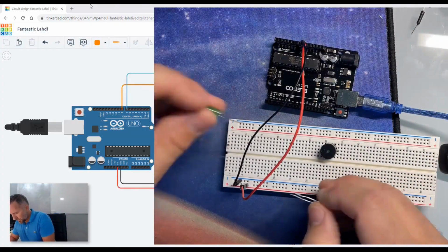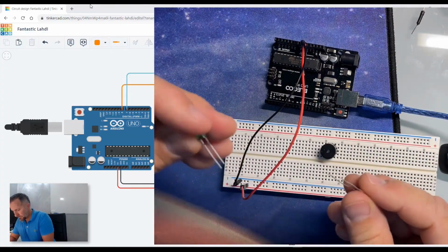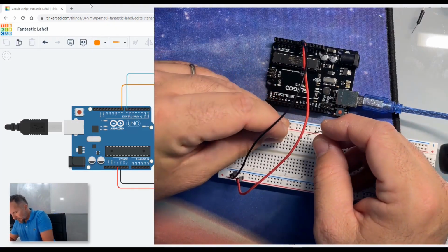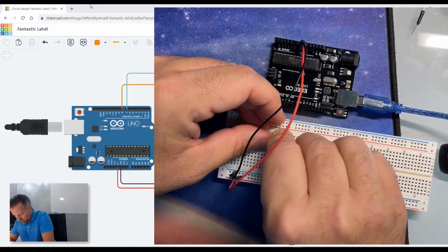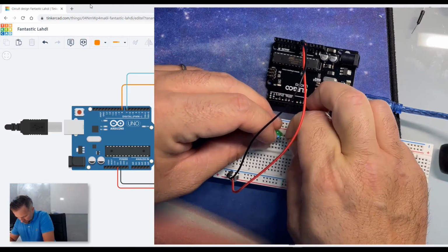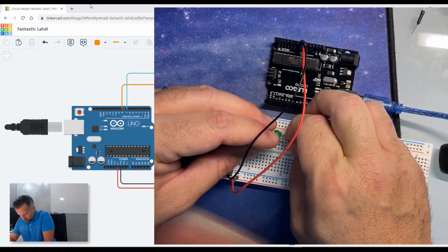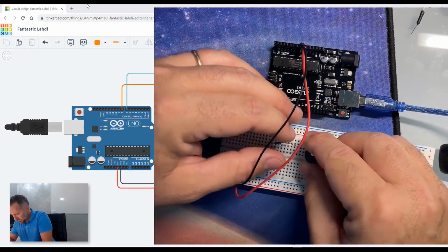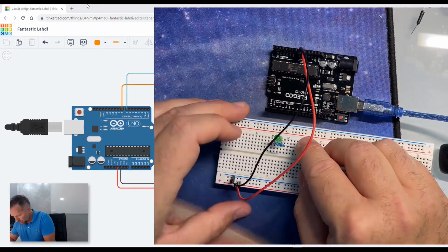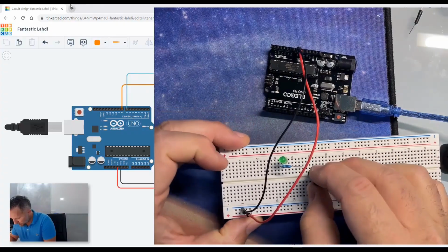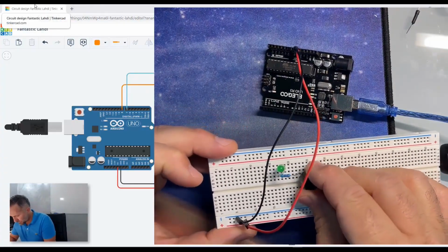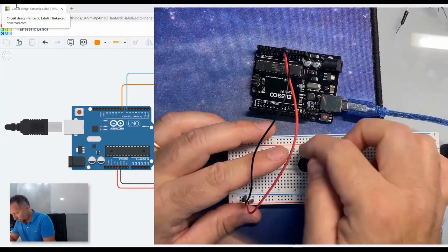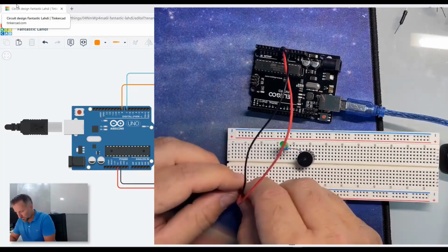We set up an LED that can light up together with the buzzer. So we place them on the same row. Then I connect the end of the resistor that powers the LED, the anode, with the positive of the buzzer. In this way, by powering a single row, we will power both the LED and the buzzer.